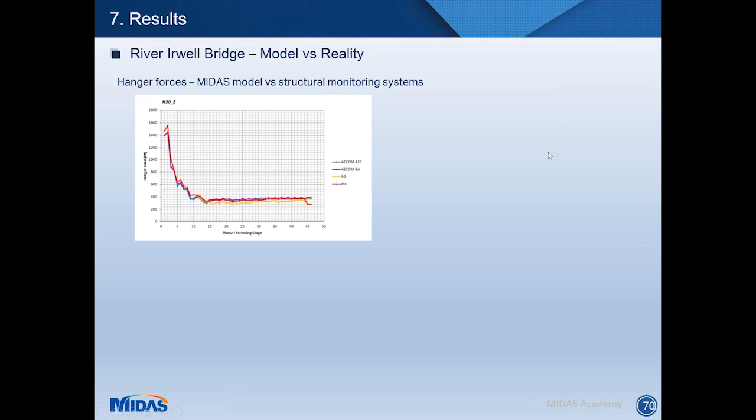Okay, we're good on time. Last slide. I'm just going to show here how the MIDAS model predicted the behavior of the cables on site, and how by using a detailed analysis during construction, matching the displacement of the red on site, we managed to get even better fitting. So these graphs show in the red curve the PIN structural monitoring system reading. This is an ultrasound based structural health monitoring system. The yellow line is showing the strain gauge system used on site.